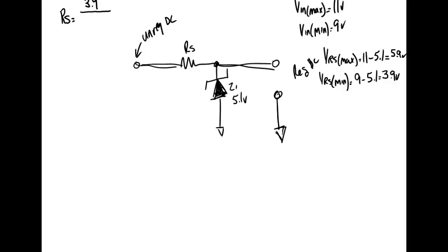Okay, so what current are we going to use? Max plus IZK. Yeah, because what we're trying to do is make sure of this. So what we need to do is figure out what IZK is. So where did y'all find it? Yeah, so what we're all doing is the 4700 series. You got your worksheet? Yeah. So we'll look up IZK. So our maximum current is 10 milli, and then we're going to add to that our IZK we're going to get from our data sheet. What did you get, Drew? 1 milli? Okay, so we're going to use...